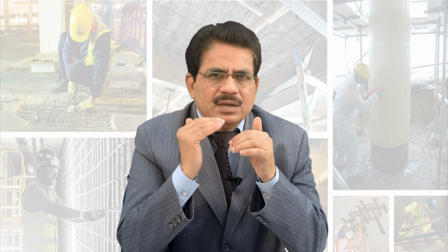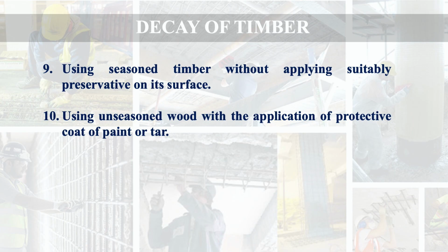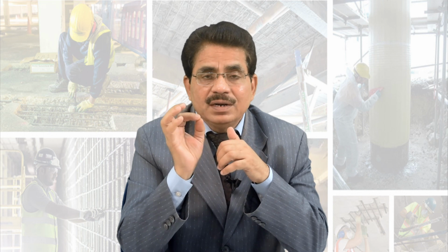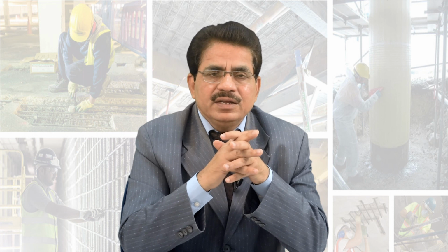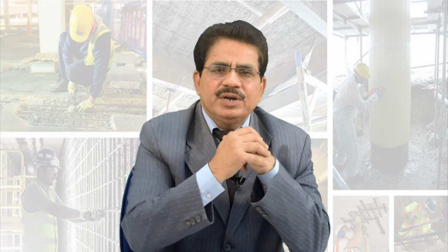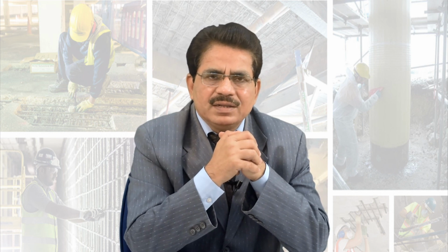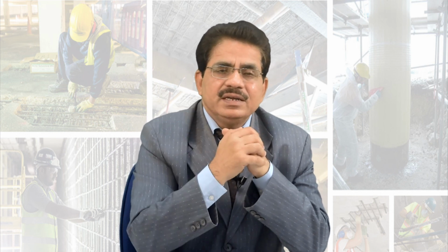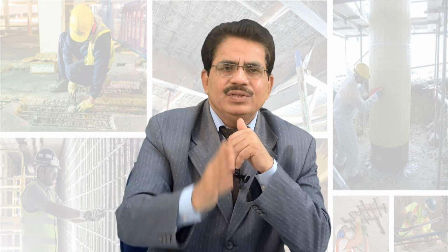Then another reason may be using unseasoned wood with the application of a protective coat of paint or tar. One very important defect is that if you are using unseasoned wood and applying the protective coating of paint or tar, then it is certainly going to decay. So these protective coatings should be applied only on the seasoned timber, not on the unseasoned timber.